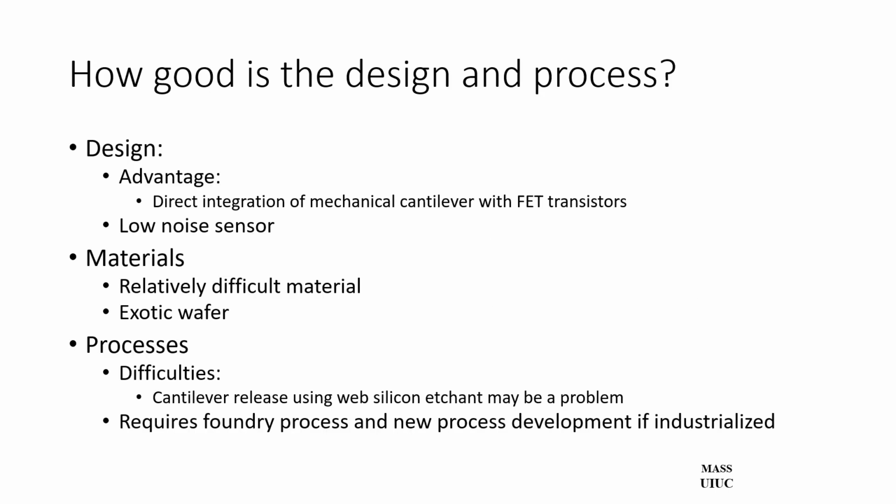So what are the pros and cons of this? Right, the design aspect. The good thing is that this allows the mechanical cantilever to be directly integrated with field effect transistors. So you could have a low noise sensor because the electronics and the sensors and actuators are together.